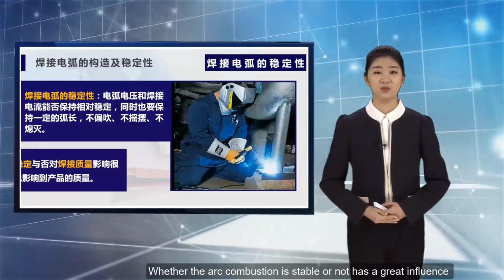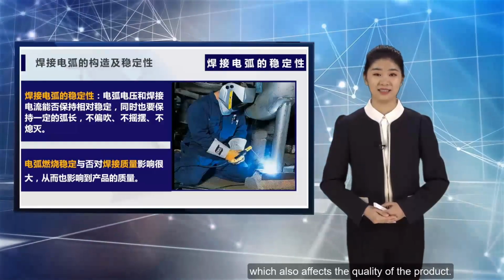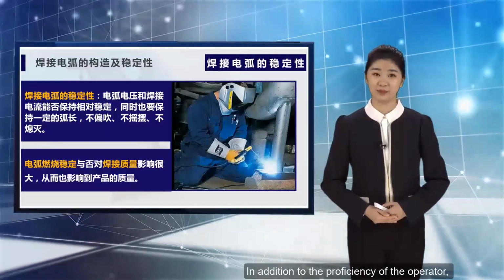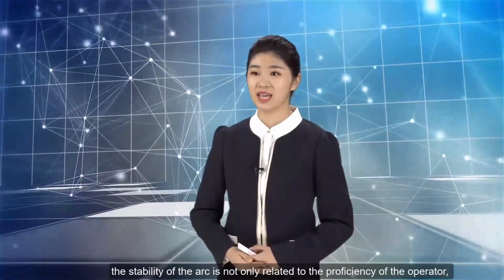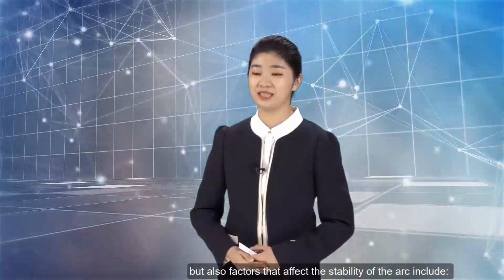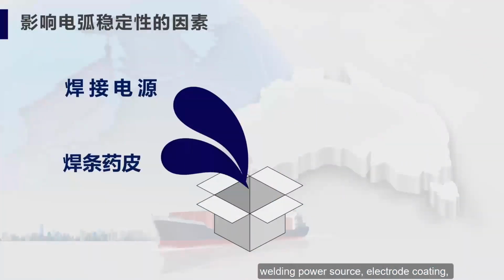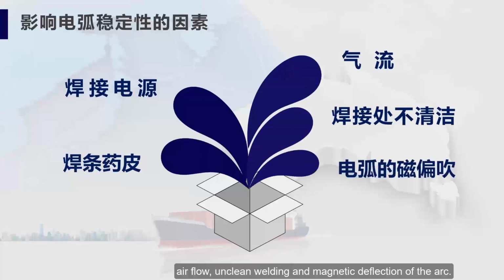Whether the arc combustion is stable or not has a great influence on the welding quality, which also affects the quality of the product. The stability of the arc is not only related to the proficiency of the operator, but also factors that affect the stability of the arc include welding power source, electrode coating, airflow, unclean welding, and magnetic deflection of the arc.